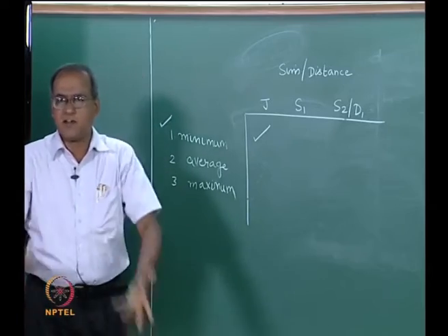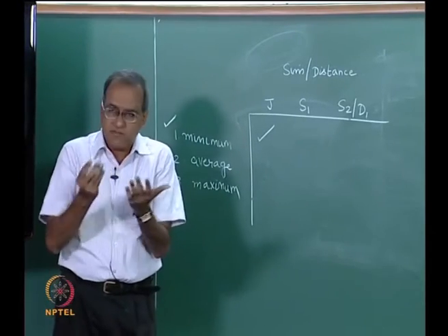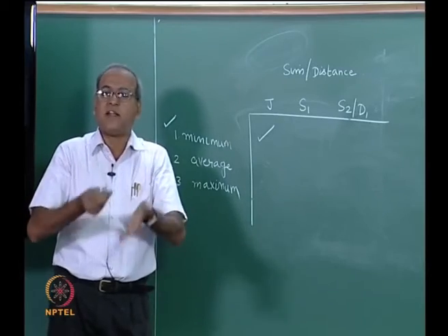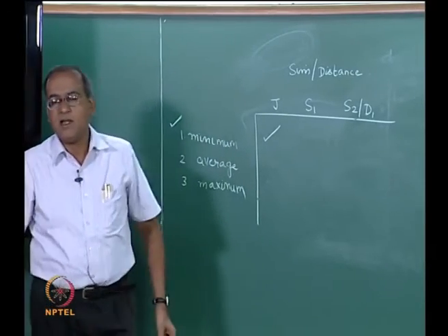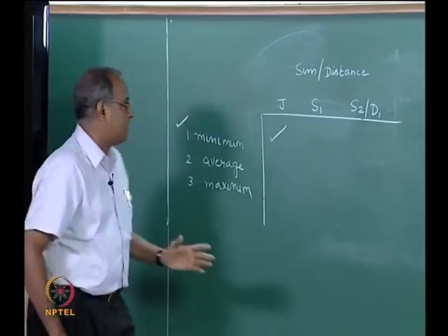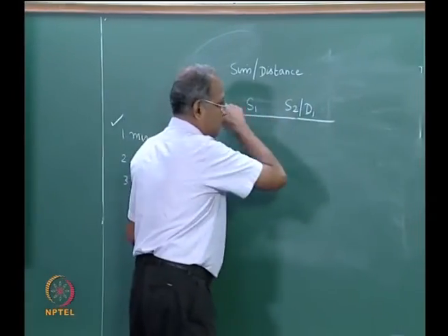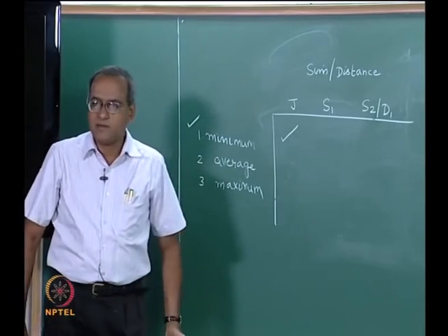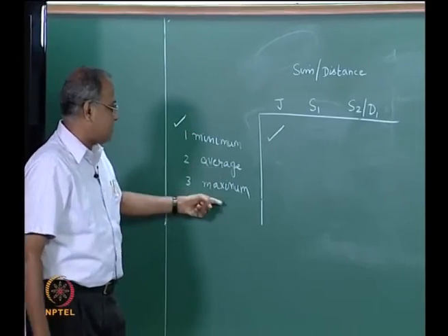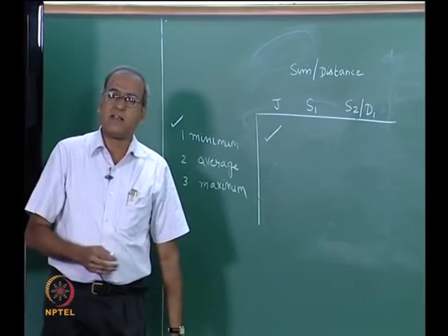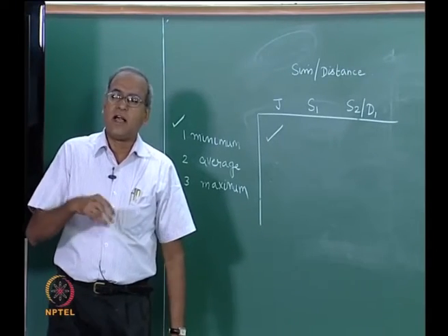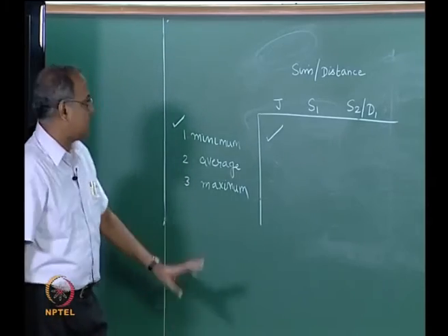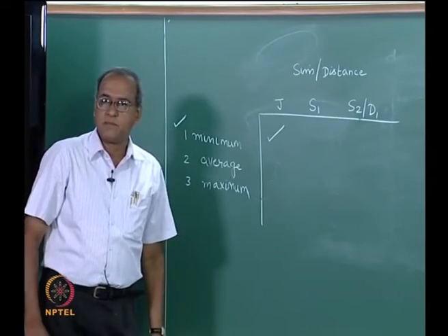Many versions of clustering algorithms for cell formation using similarity and distance methods are available, and they largely differ in the way the similarity coefficient or the distance measure is calculated, and in whether it is a complete linkage, a single linkage, or an average linkage cluster analysis algorithm. So, we have represented only one of them.